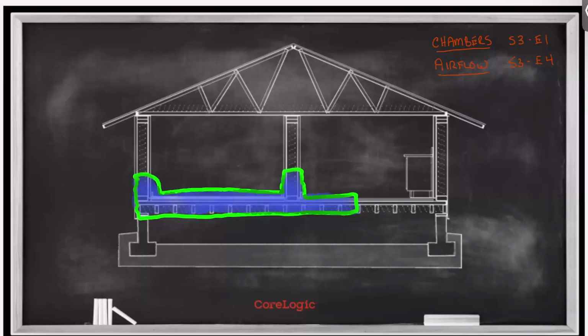So all of this is affected within this particular structure. A drying chamber looks at the depth of that water penetration into those assemblies and into those materials. And what we have to do is establish airflow, circulation, or communication between the air in and around all of the wet materials throughout that space. And that may require that we have one or more drying chambers. And to drill that a little bit deeper, a single drying chamber may be adequate to deal with most of this wet area that I've just identified. But in this particular case, I know that we're going to need at least two.